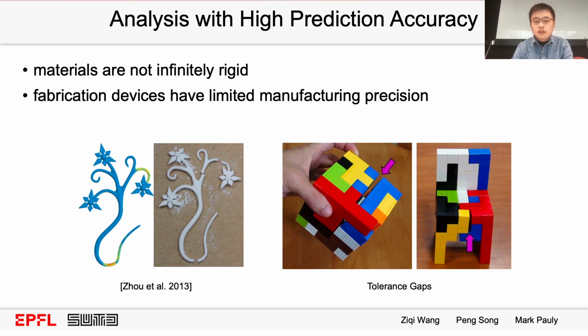As a consequence, structural issues can arise when the relative motion of 2 parts is restricted by a small contact or a thin joint. Internal stress concentrations at the contact or joint can lead to material failure. Similarly, a geometrically stable design could become unstable when fabricated due to gaps among the parts caused by machining tolerances.